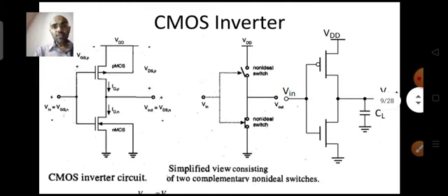We'll try to understand these voltages for NMOS, and then for the PMOS also. You see, the source terminal of the NMOS is grounded, whereas the gate is connected to some voltage which is Vin. If I ask you what is VGSN, VGSN is nothing but the potential of the gate terminal with respect to the source of the NMOS. N denotes the NMOS.